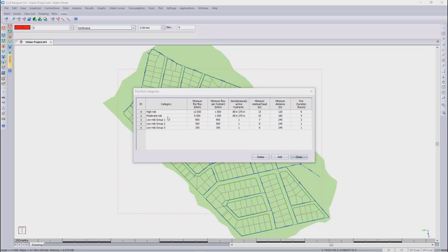Restrictions in force control the height and the area of the building materials used in the construction and the distance from the common earth boundaries. Attached dwelling units are separated by a firewall with a minimum fire resistance rating of 1 hour.